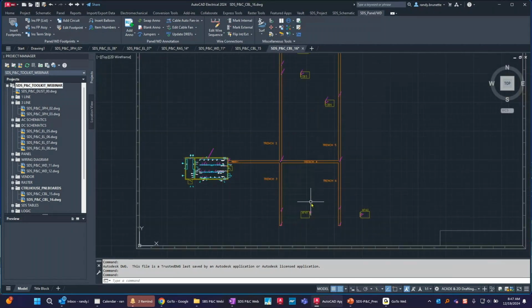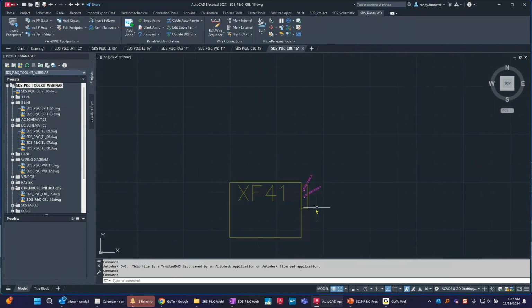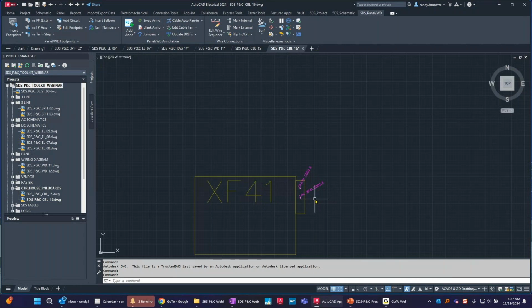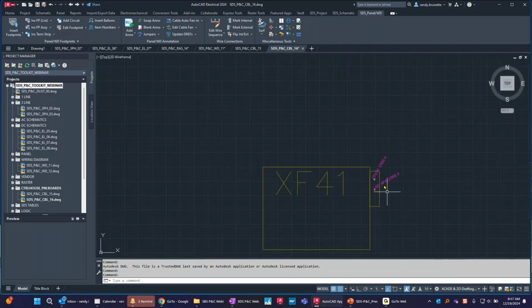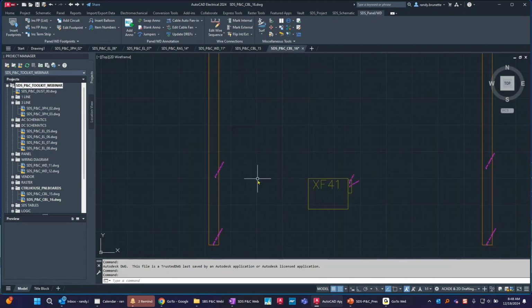What we're doing is we're putting in work points. We're calling them that, but they're really like waypoints. Where do cables start from? How do they get routed through the yard back to between components, back to different panels? As an example, we start with this one, that this is the location, it's XF41, and we're telling it to enter this conduit path, right? C path is listed here. From there, C path goes over to the other end. You'll see CO2.A. .B is now entering a trench.